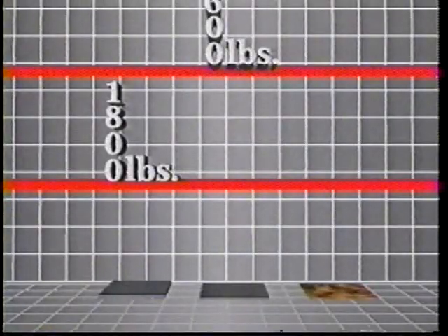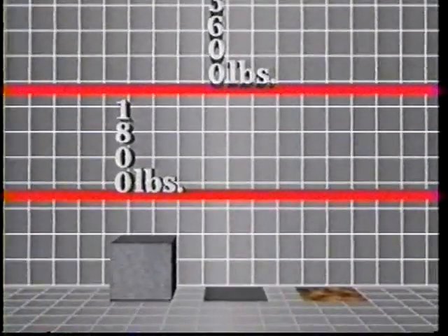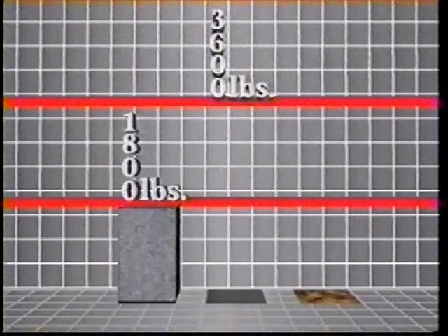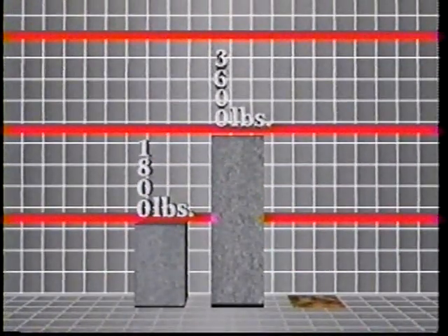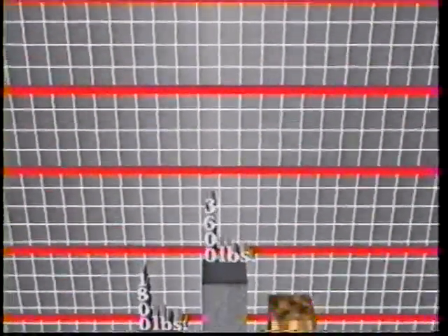While standard asphalt mixes rarely demonstrate stabilities even 50% above the minimum stability requirement for the heavy traffic classification, it is normal for road oil resin concrete pavement mixtures being evaluated by independent testing laboratories to produce stabilities that exceed the minimum stability requirements by 2, 3, 4, 5, even 6 times.